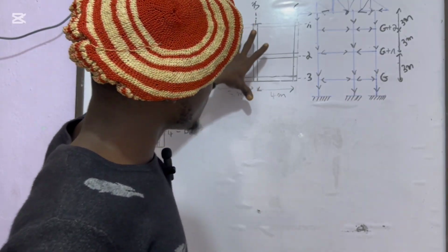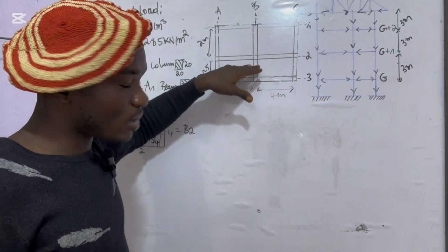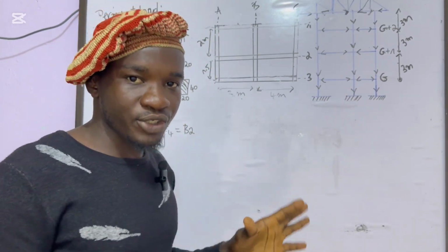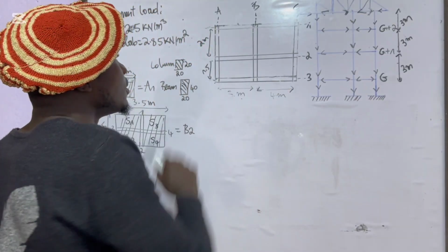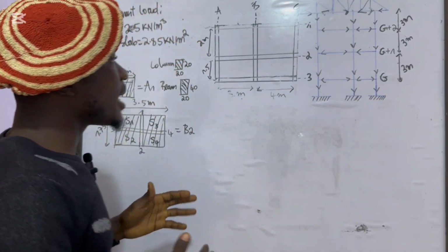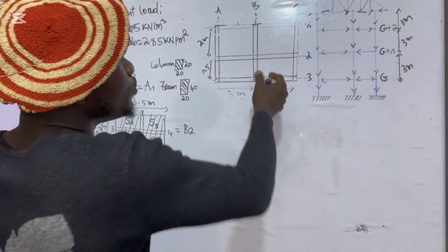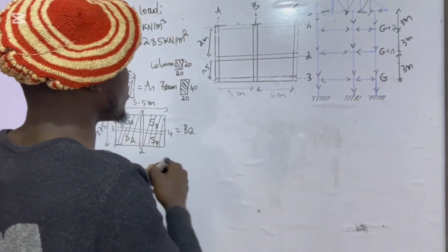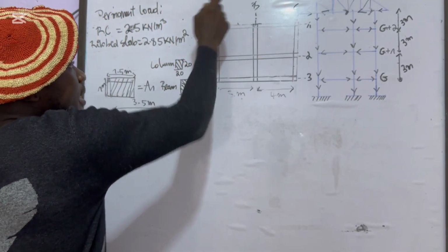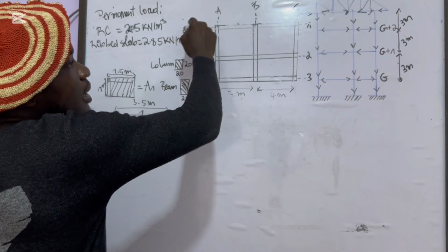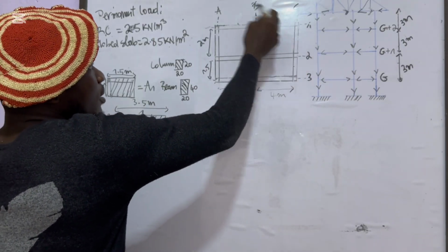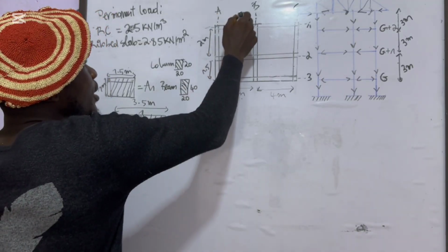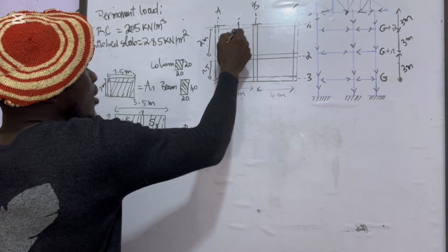Here you have a 2D representation of the floor plan of one level, considering the spatial organization has not changed. How do we get the load applied on this column for the design of the reinforced concrete column? If we consider the case of axis A and 1, the intersection of A and 1, you have the column A1, which is at the angle here. The influence area will be divided at the center of this beam.